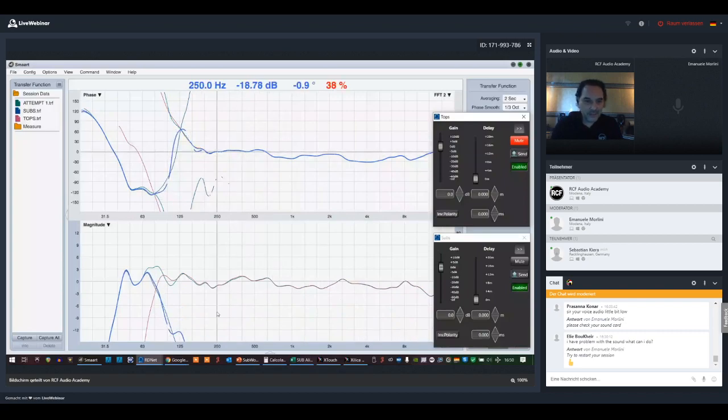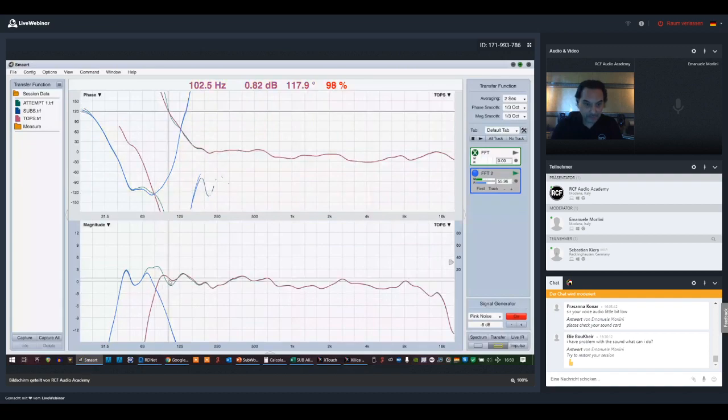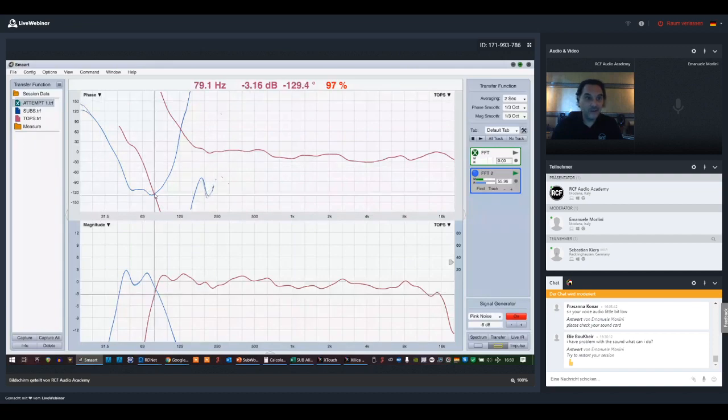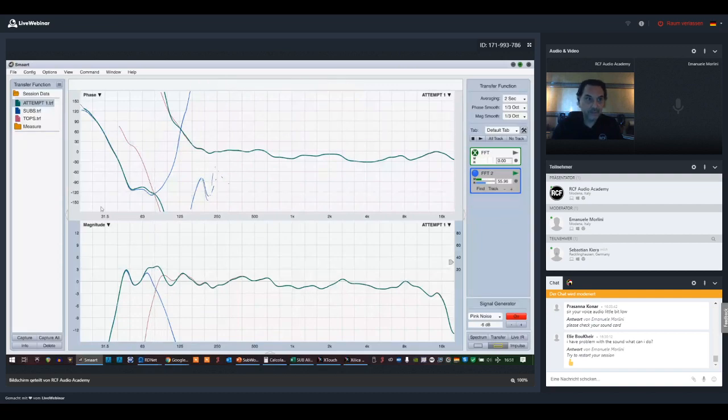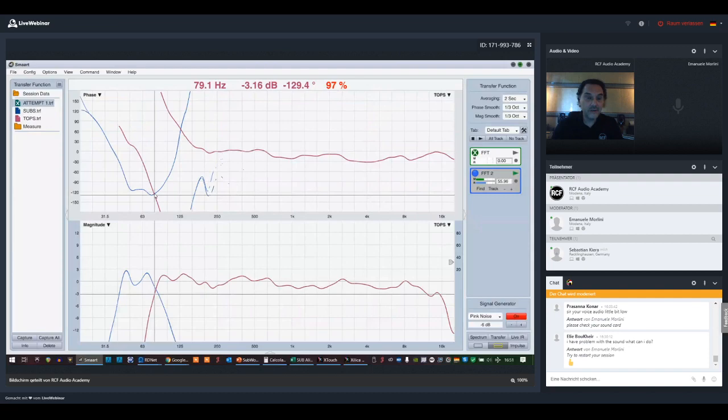But you can see that here we have a cancellation because just the top had more SPL in this region. But of course, we are lucky in the crossover zone. In fact, we have almost 6 dB of summation at this point, but not in the surrounding frequencies, because the phase traces are absolutely not overlapped. They are overlapped just at the crossover point.